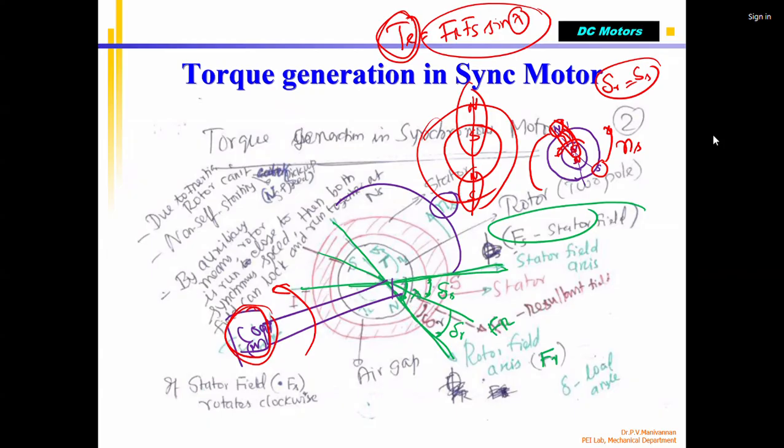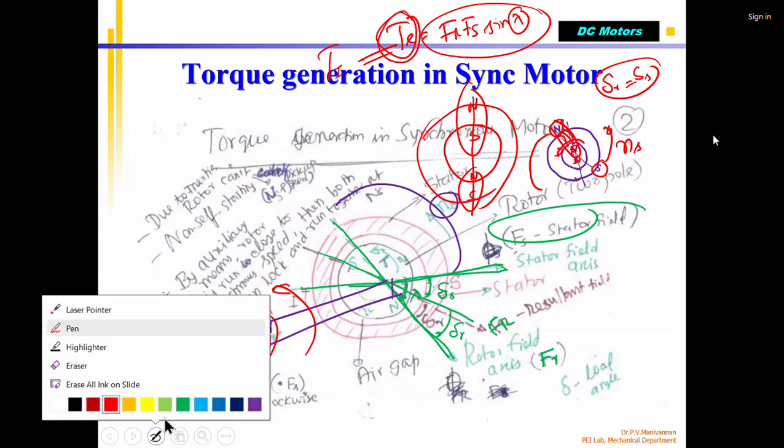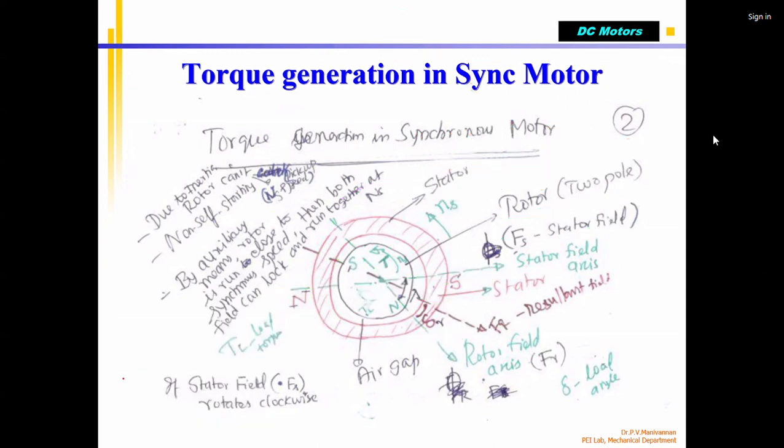That's why we say a synchronous motor will run at synchronous speed, and it can take load until the generated torque is not sufficient for the inertial torque, Ti, that depends upon mass, correct? All this mass together. Thus, when the inertial load is more than the torque generated, the motor stops. They call it the stalling torque. Okay, so this is one thing.